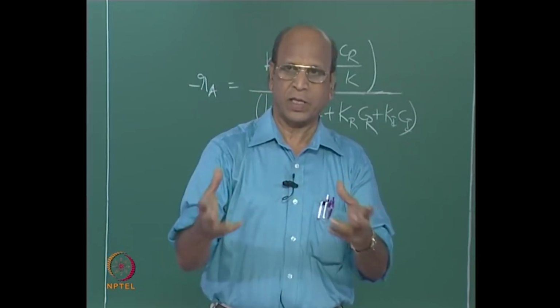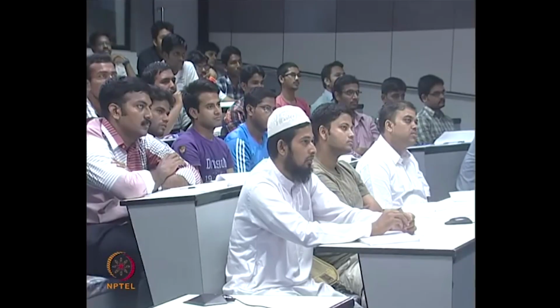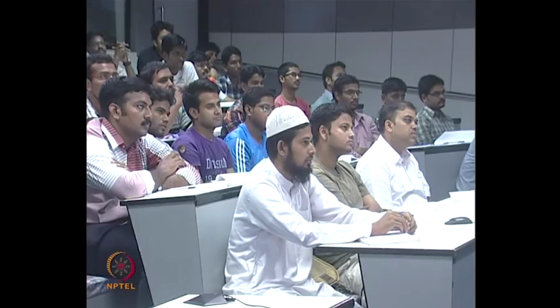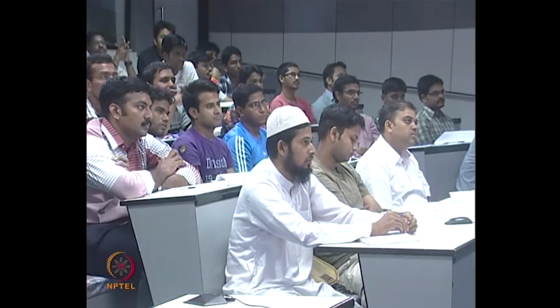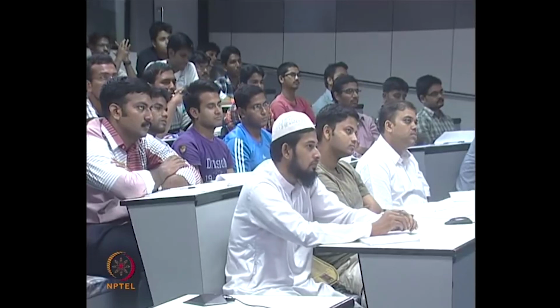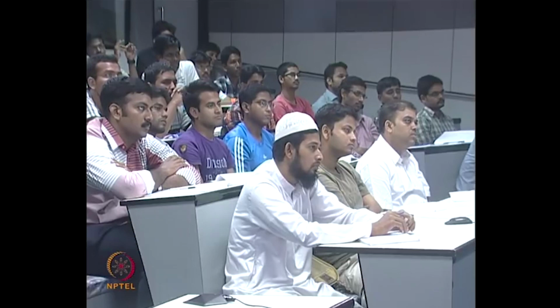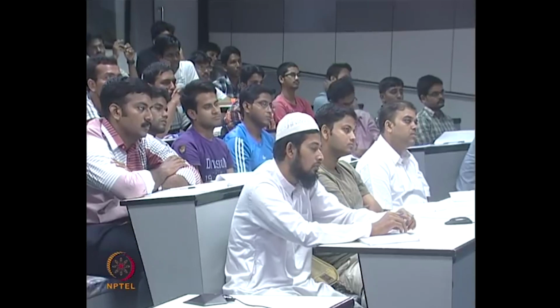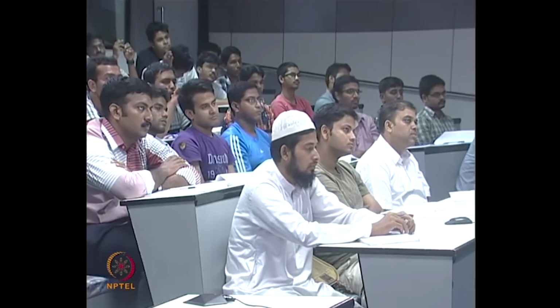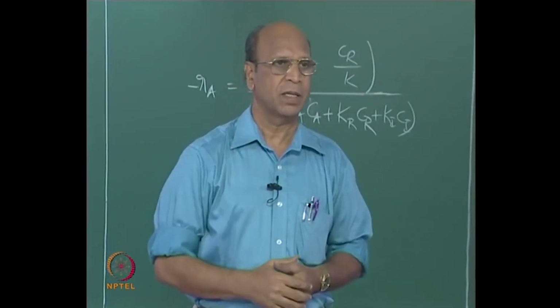Yeah, but what does that finally give you for this procedure? Number of stages? It will not give you a number of stages. Thermodynamics will give you only the equilibrium diagram. So, from thermodynamics simply take the equilibrium diagram. Okay, if you are assuming even enthalpy, it is the simplest case. And then from energy balance, from material balance, you will get the operating lines, correct?